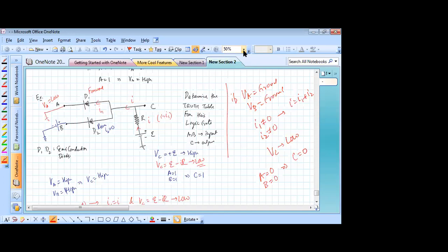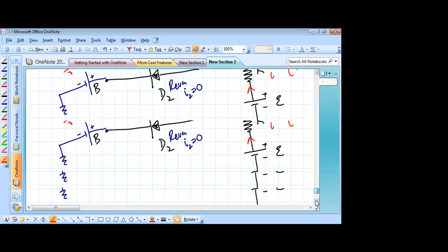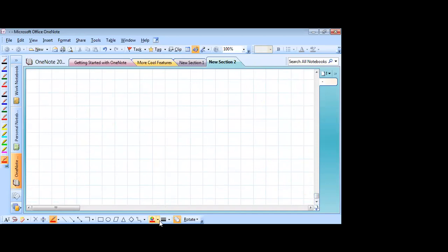Right, so hope this thing is fully clear. So in digital circuits, because we implement a very large number of such logical gates, we develop short forms for each one. So that whole gate that consisted of the two diodes, the resistor and the cell, that is now drawn as a short symbol like this.